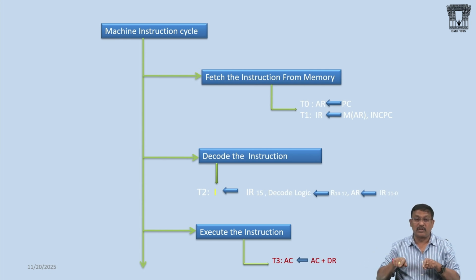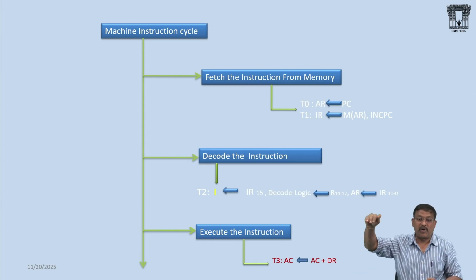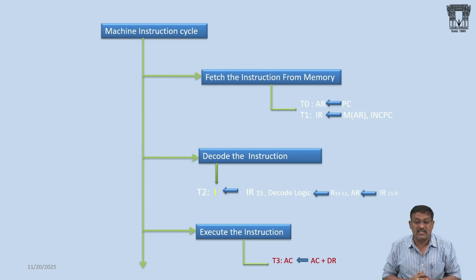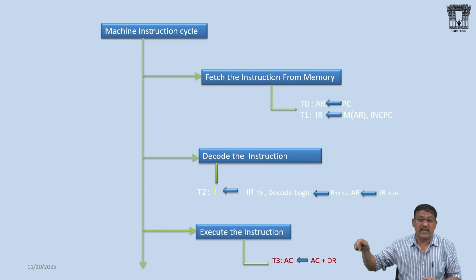Similarly, F400 is the code of the OUT instruction. Out the data; specify the destination address: OUT 82H, comma, accumulator. That means transfer the data from the accumulator to the output device. The address of the output device is represented within the instruction. You got my point? OUT 82H, accumulator. The source of the data is the accumulator. The destination device is my output device. The address is represented within the instruction.